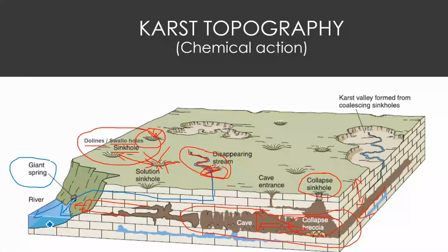So when we are going to decide on this area for construction purpose, for example, if you are going to construct a building here, this area needs to be taken into consideration. There are a number of things we can do. One thing is that if you understand this region completely, okay, now I understand there is a karst topography, and the karst topography is basically based on the rock type. I understand this rock type also, this is a limestone.